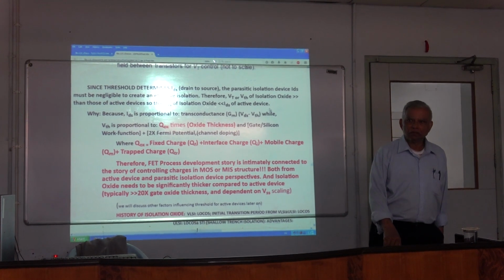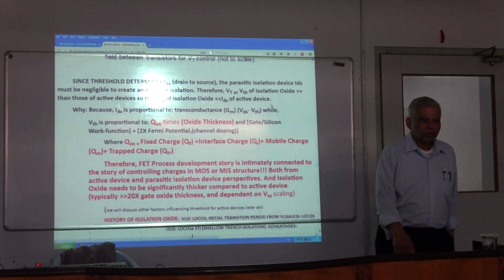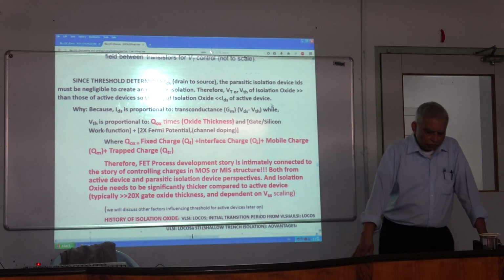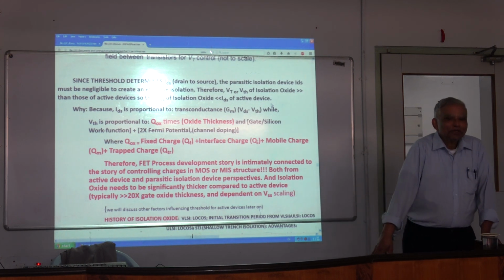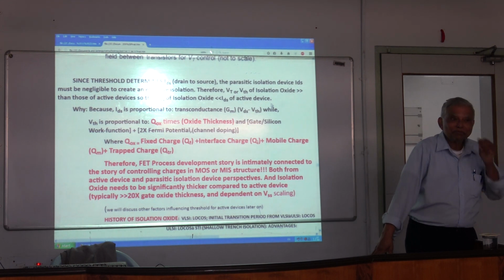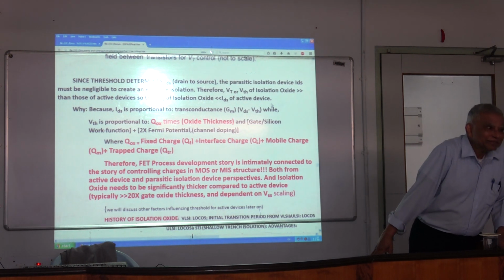When I first started, the technology was developed as a P-channel FET technology. And the reason is, can you tell me the reason? In the P-channel technology, the threshold is negative. It's always conducting.